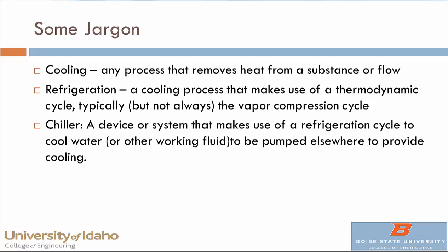I say almost always because you might use absorption or adsorption, which is a way of using heat to refrigerate. A chiller is a specific kind of device, a hardware, that uses the vapor compression cycle. So it has a compressor, an evaporator, a condenser, but it's all self-contained, and it exchanges heat with another working fluid, usually water or a water-glycol mix. So a chiller has a refrigerant and a refrigeration system, but it's all self-contained, and what's coming and going and interfacing with either the building system or the industrial process is a secondary fluid, and that's usually water.